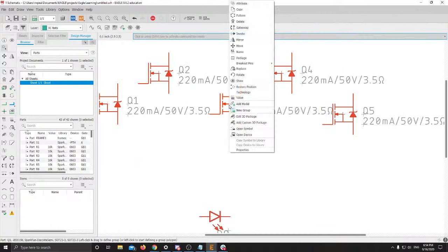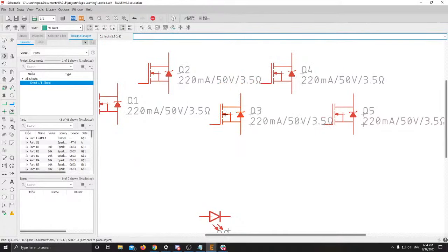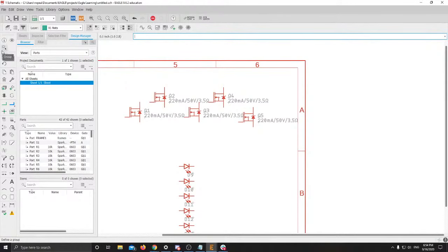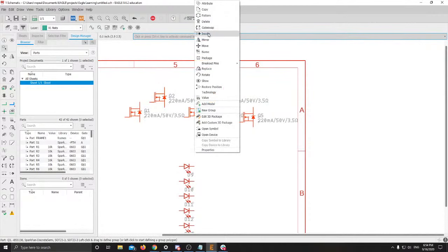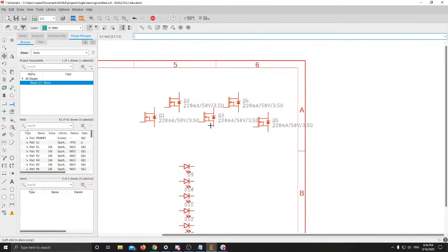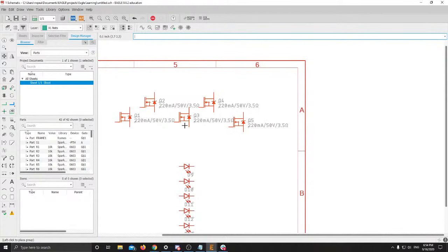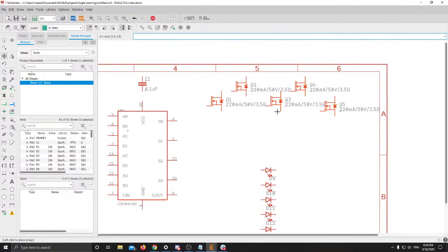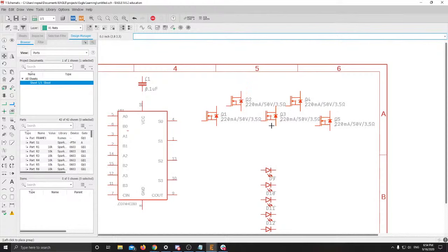then I'm going to right click on one, select the option that I want, it'll select just that, then I'll hit escape, it'll send it back, then I'll right click anywhere that's not on one of the parts and do move group. And apparently I messed it up. So highlight them all, right click, move, moves one, hit escape, right click again, move group, and it should select all of them. I don't know why it's so convoluted to do that, but that's what the Eagle developers decided to do.